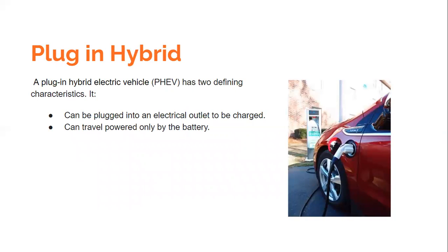So how do they operate? PHEVs start in all-electric mode. So the starting is in electric mode, then it runs on electricity, and when the batteries are low in charge, then the internal combustion engine supplements or it boosts the charge of the battery pack. So internal combustion engine in these vehicles is a supplementary kind of thing.